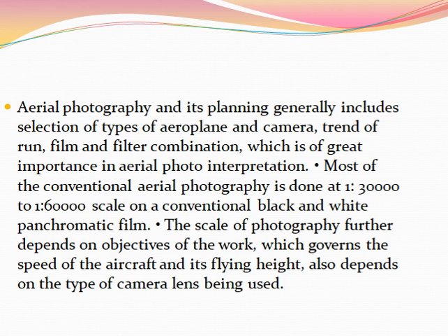Most of the conventional aerial photography is done at 1 is to 30,000 to 1 is to 60,000 scale on a conventional black and white panchromatic film.